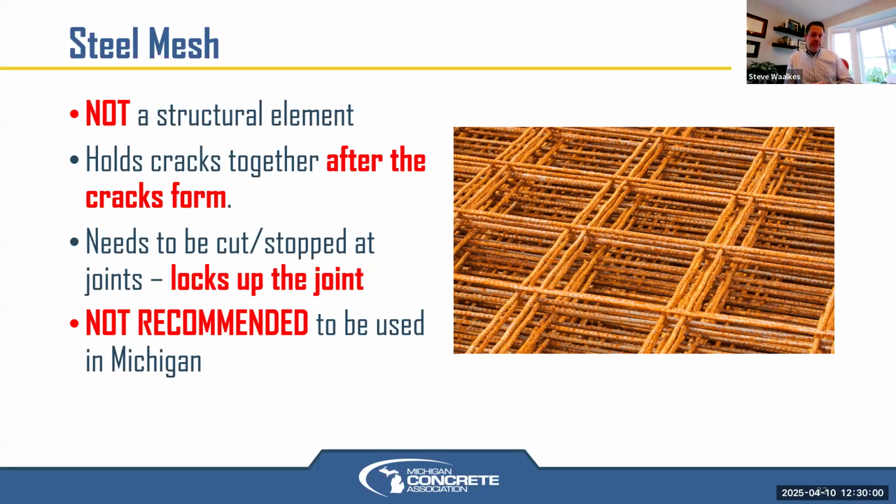But I've seen some private facilities with heavy duty manufacturing and unique loading situations with heavy duty non-pneumatic tires, foam filled rubber or hard rubber tires where 14, 15, 16 inches are needed. I've seen FAA facilities, most recently at DTW, do 21 inches of concrete, I believe. So yeah, it all depends on what's driving on it and what it's supported by. So good question.